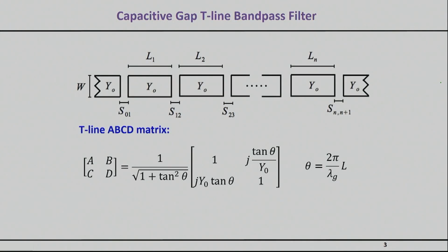So first of all, let me show you how the filter will look like. So there are going to be a bunch of transmission lines. Each one of these squares here shows the layout of a transmission line section. And here you can understand we're talking about a microstrip line. So this is essentially a top view of the filter. And the coupling of energy from one resonator to the next will actually be realized by bringing these transmission lines close to each other. So physically, we're going to implement the coupling sections by basically bringing the transmission lines close to each other.